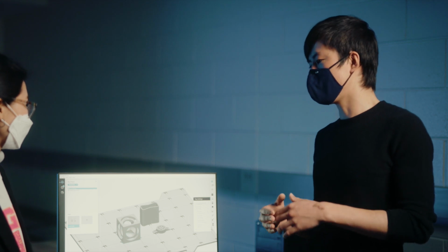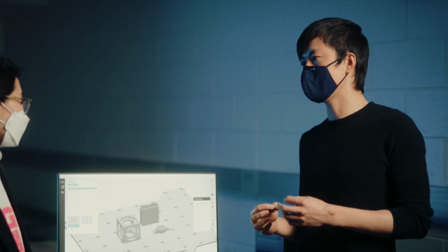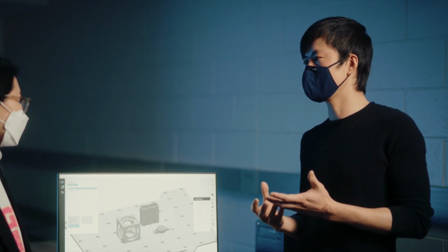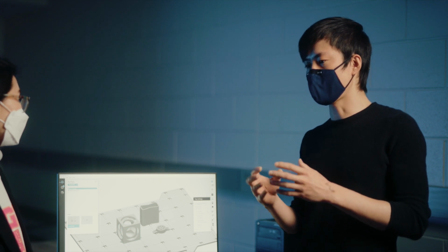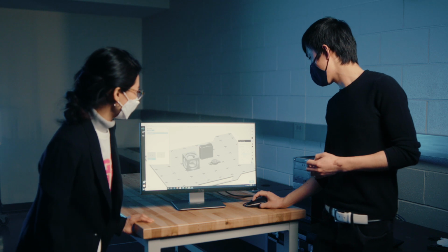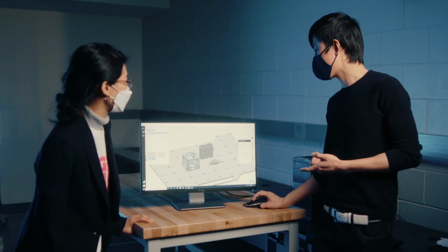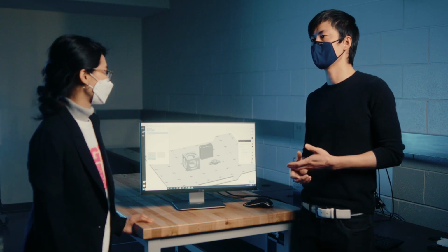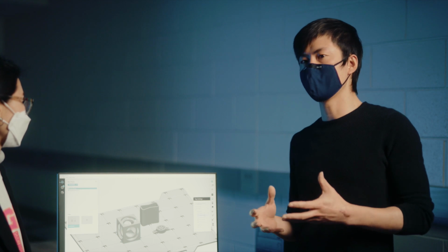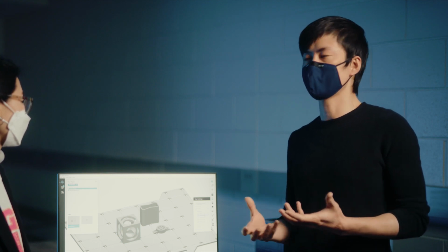Imagine if you want to print a sphere, if you have a very thick slice, the sphere surface will not be as smooth as you want it to be. It will feel very rough. If we decrease the slice height to the minimum thickness, which is 0.005 inches, the surface will feel very smooth, almost like a real sphere.